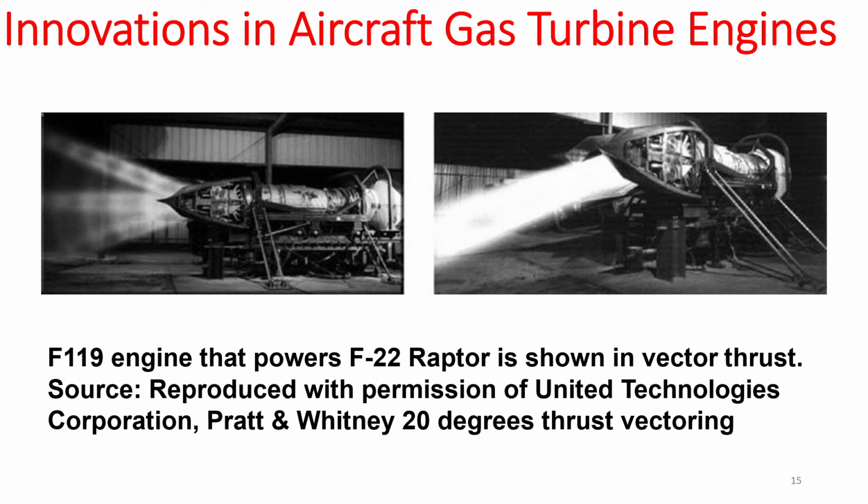This is an example of the F-22 thrust vectoring mechanism that changes the direction of exhaust. As you can see, it goes from negative 20-degree thrust vector to a positive 20-degree thrust vector. Thrust vectoring is something that you will hear about in your aircraft design. We'll hear more about it in aircraft design. We will talk a little bit about it here. What are the applications of thrust vectoring? But essentially, it means that your exhaust gas angle is changing.